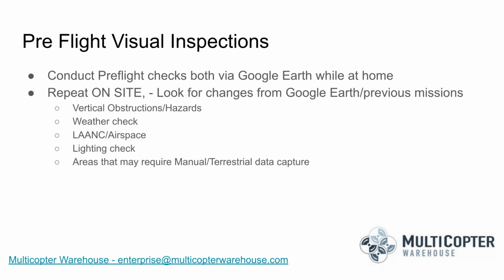Yeah, for true agricultural type of work, you really need to have what we'll call a narrowband multispectral camera. And when I say narrowband, like the DJI Phantom 4 Multispectral has 6 sensors on it that are detecting very narrow bandwidths of light energy.